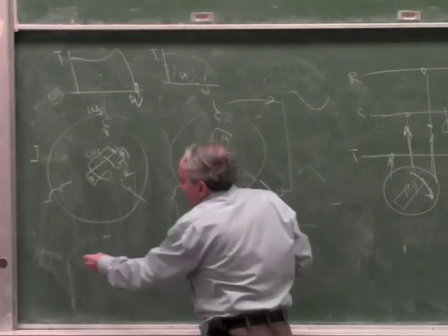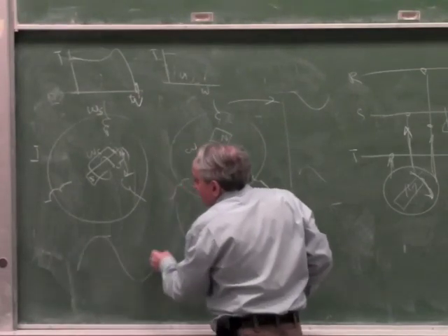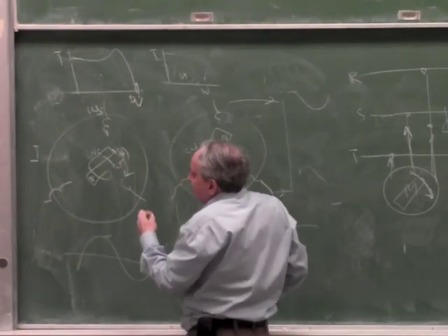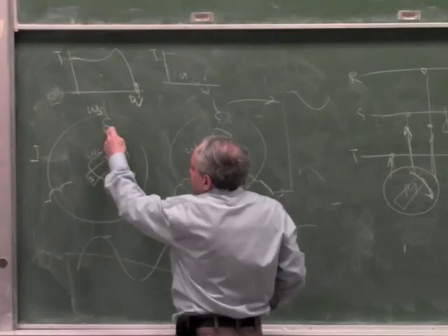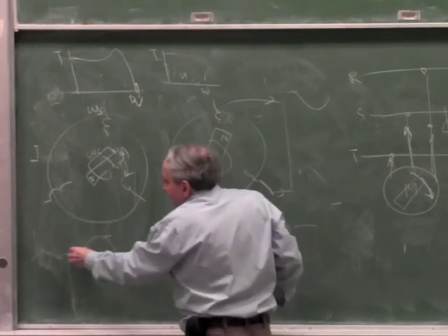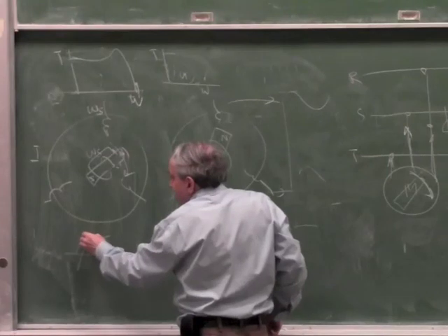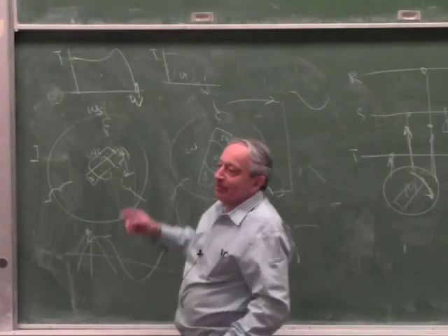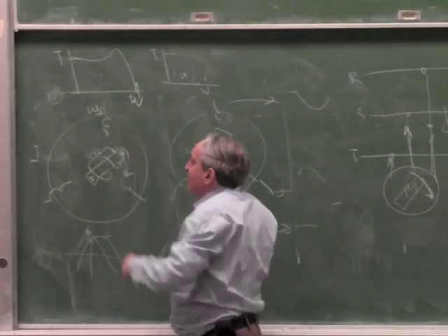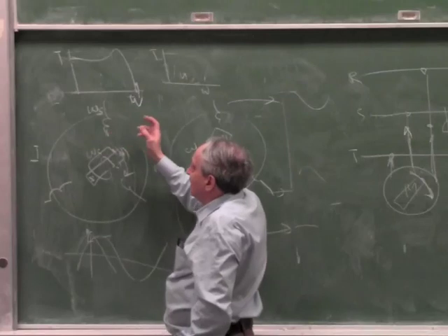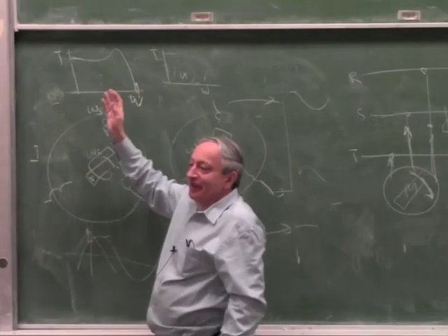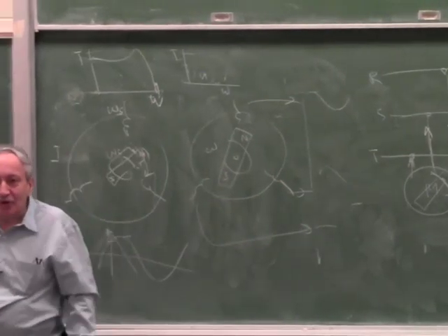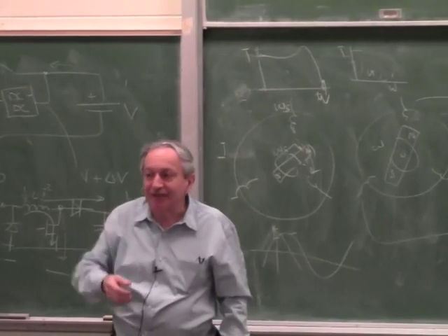Imagine this is the input voltage, and you manage to turn this faster, and momentarily there was an EMF which was higher than this voltage. It's only higher because its phase is advanced, like this. So momentarily, it will actually feed the power back. If you continuously feed it, so that this EMF is at the right phase and higher voltage, power will flow back. So even in an induction motor, if you overdrive it mechanically, it can feed power back.